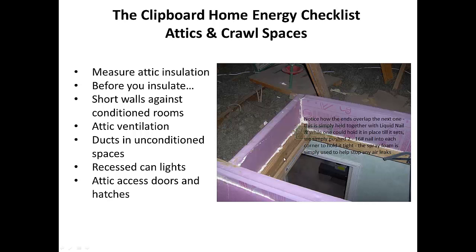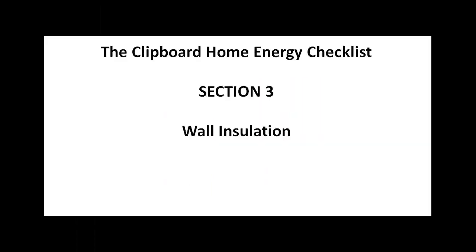Here is an attic access, and you can see there's the spring right over here where it's lowered down. And what they've done here is use a couple inches of rigid blue styrofoam insulation, and they've caulked it with foam caulk, those cans of foam like Great Stuff, so that when they add insulation, they can get a higher level of insulation without it falling down into the stairway every time they open up to get into the attic to check something out.